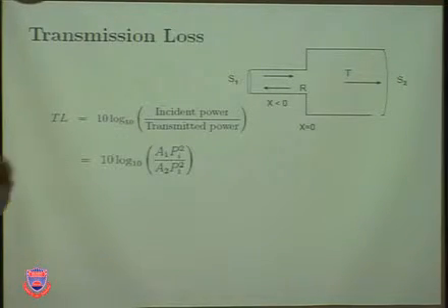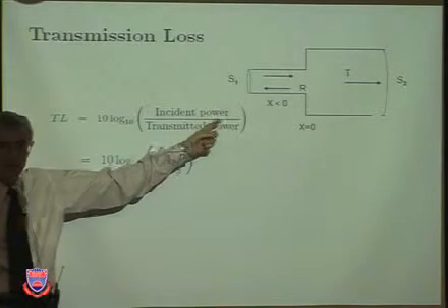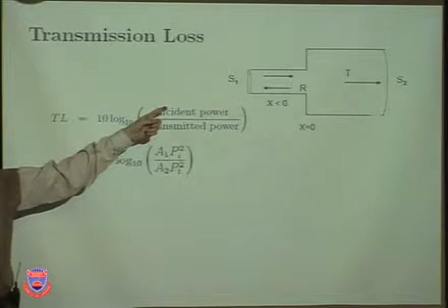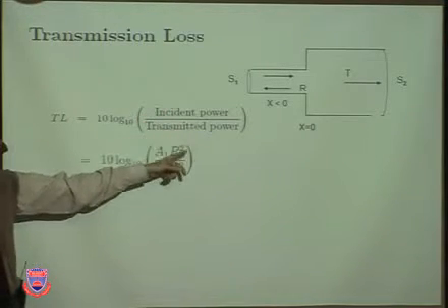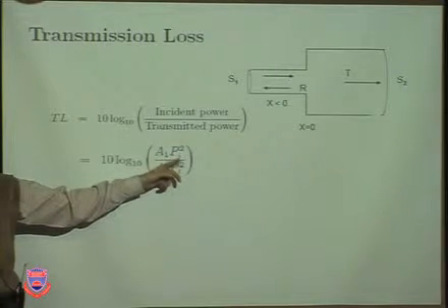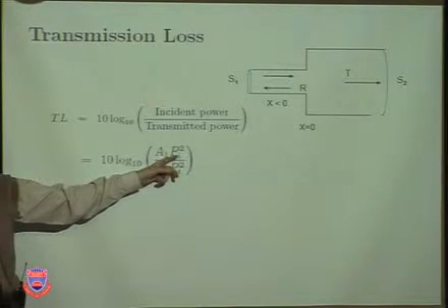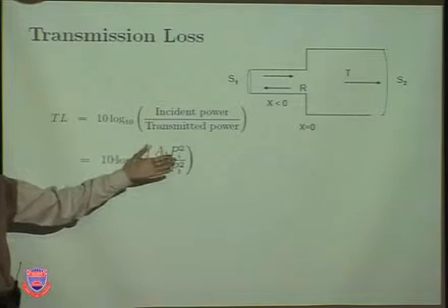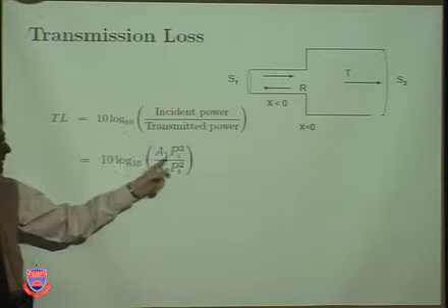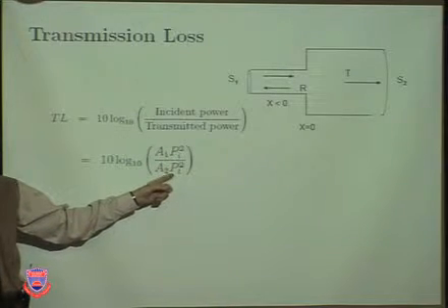And because it says power, okay, and because power is area times an intensity-like quantity, intensity is pressure squared for plane waves, divided by the specific acoustic impedance, but this is the same fluid, so we use the same one.